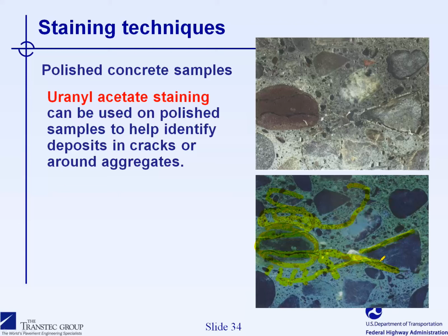Yes, generally speaking, the water-soluble alkali content that you will measure will be the alkalis readily available from the cement. The alkalis incorporated in the supplementary cementing materials in general will not be released during that test.